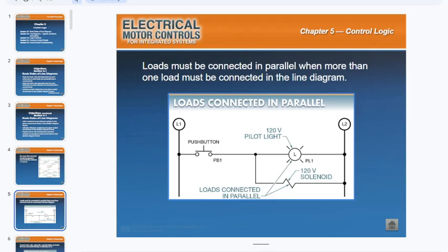But here's the reason why I don't like that. What this is telling us when that little dot is right there, and for in-person, now that you guys have built a few labs, and I'm sure that you've had this little dot on a line or on a rung, sorry. What this is saying is, hey, this wire that's leaving that solenoid going into rung 1, it doesn't have a home yet. What that little dot in the middle of the rung is saying is find a place to put that wire.